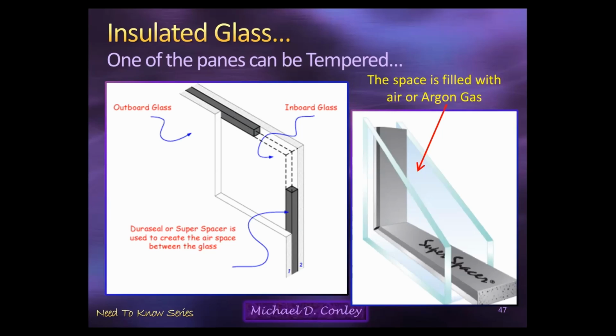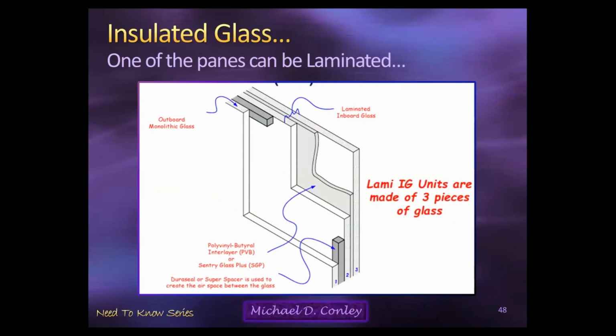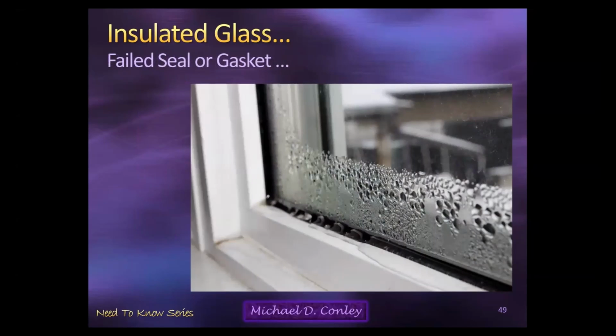While you're looking at dual panes, boy, that was hard to say. You've got to look in each one of these panes of glass to make sure they're still clear, because what happens is either the gasket will fail or something will cause the argon gas to escape, and that creates a partial vacuum, which will allow moisture in the air to be drawn inside the glass, sometimes to the point where we actually see rain inside the pane. Here's a good example right here.